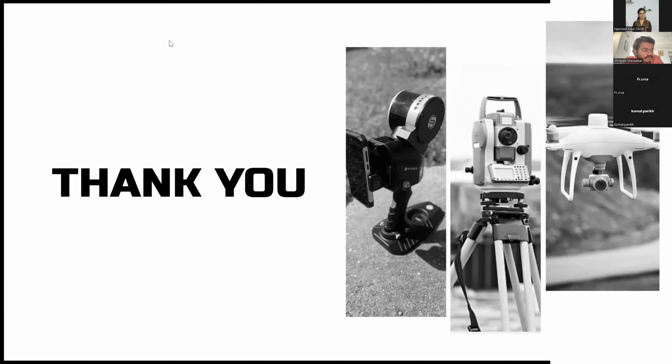But what we are trying to do is to see how this technology can be combined with satellite data. So what we have done over here, we have utilized total station and DGPS survey to enhance the output of the terrestrial scanner as well as the SLAM scanner or drone technology. Standalone technology is generally giving a centimeter level of accuracy. So I think with satellite data, we cannot achieve this kind of accuracy. That is one of the limitations, but at the planning stage, we can use remote sensing or satellite data for the same. Thank you.